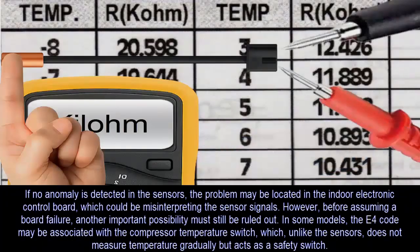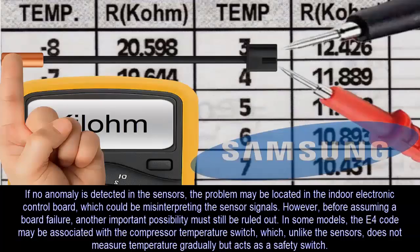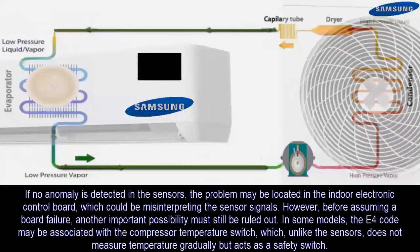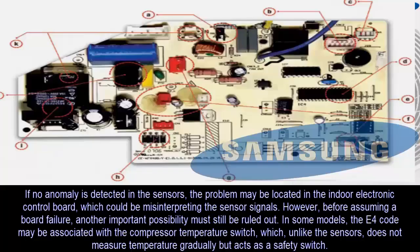If no anomaly is detected in the sensors, it is possible that the problem lies in the indoor electronic control board, which may be misinterpreting the signals from the sensors. However, before assuming a board failure, another important possibility should still be ruled out.